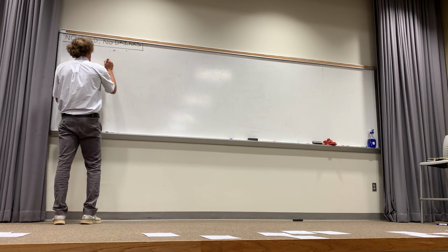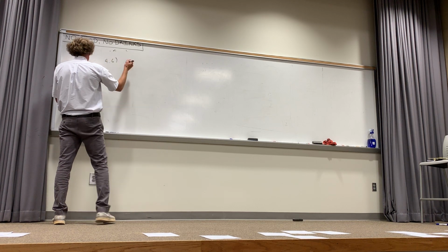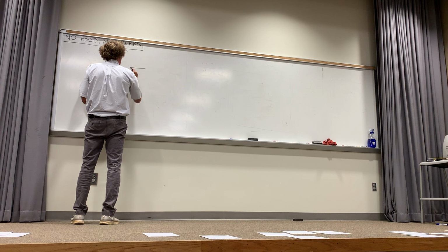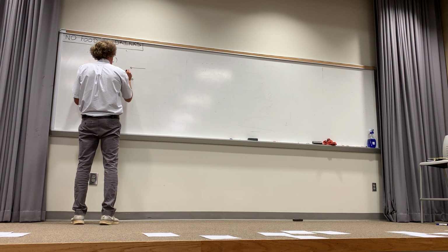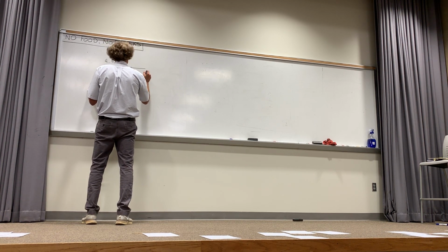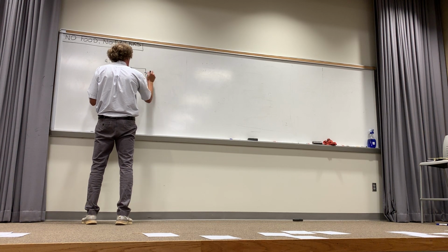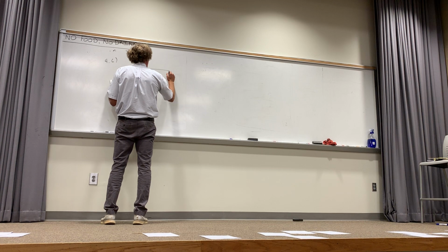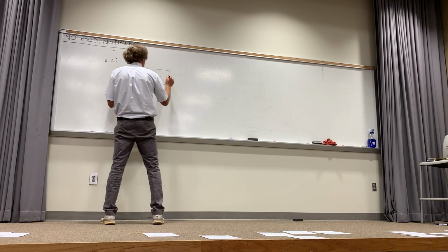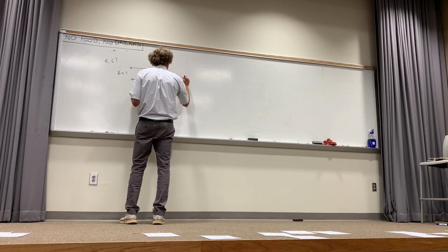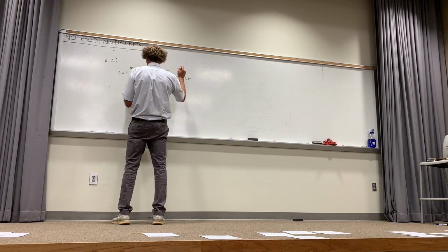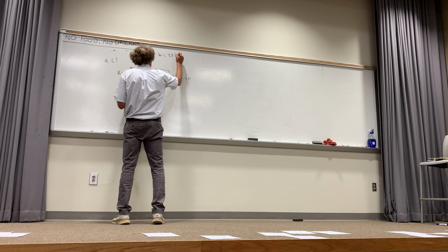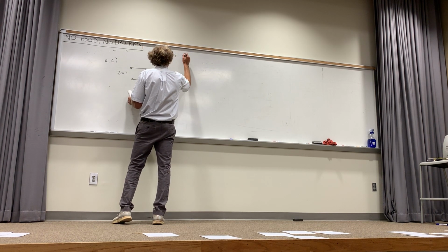Let me do a couple of these things before I get into the circuit analysis. This is 4-6 in the homework I'm going to give. It says, what is the actual impedance Z for this circuit where I have 60 ohms and L equals 0.2 Henries, and it is at omega equal to 377 radians per second.